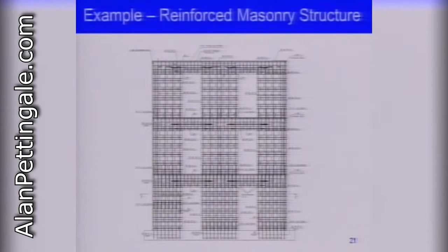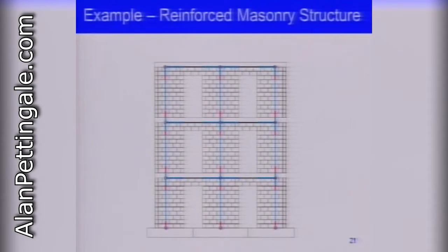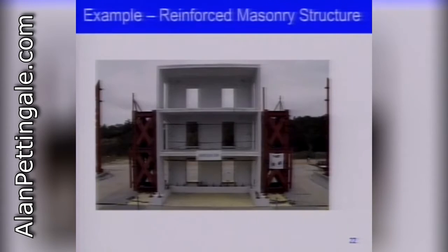So that would be a structural drawing of that structure, and this is how an analysis model would look. So we would very carefully substitute each wall with a line element that has all the properties. You see all these different width and color elements that represent different material properties and different sections, so that we can get a good representation of the structural behavior.